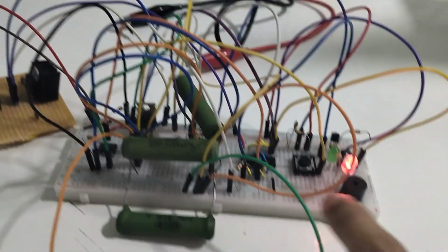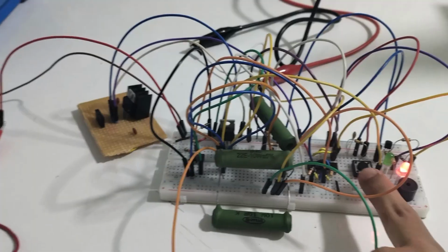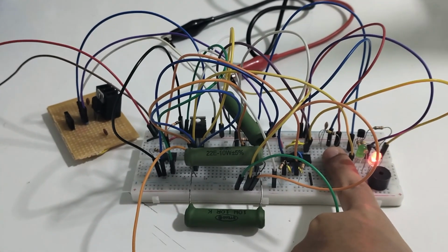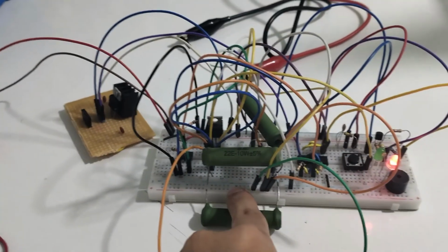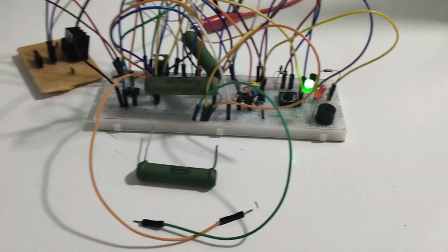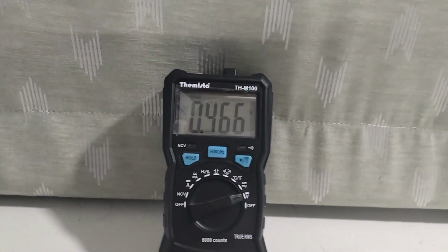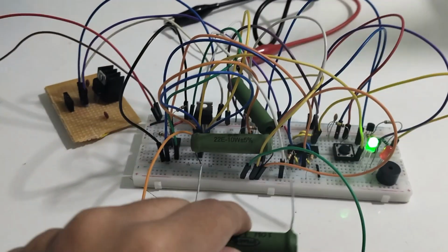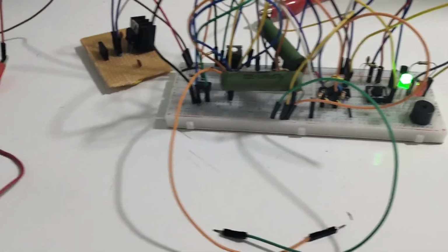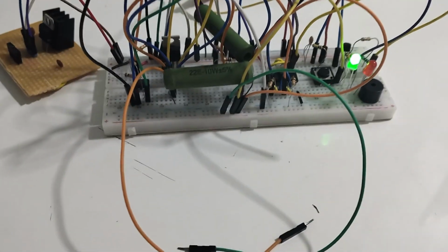What I'm going to do is press the reset switch, but you're going to see that it's not going to allow the current to flow unless the fault input has been removed. So now I'm going to remove it and press it, and you can see same as before, the output has begun to turn on and the normal current is flowing. So unless you remove the fault input, the current is not at all going to be allowed to flow. And that shows that the overcurrent protection works.